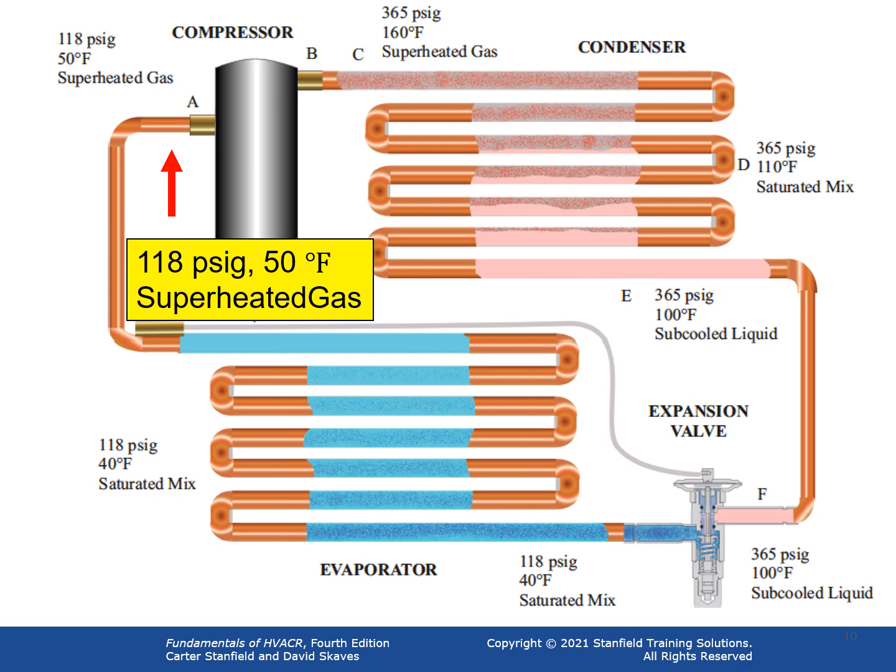The refrigerant enters the compressor as a low-temperature, low-pressure, superheated vapor. Superheating is a process of continuing to heat the refrigerant after sufficient latent heat has been added to vaporize all the liquid. Superheating ensures no liquid slugs will reach the compressor and cause damage to the compressor. Compressors are really designed just to pump vapor. This is because they squeeze what they compress. Liquid doesn't squeeze. If you try to squeeze liquid, something will break.